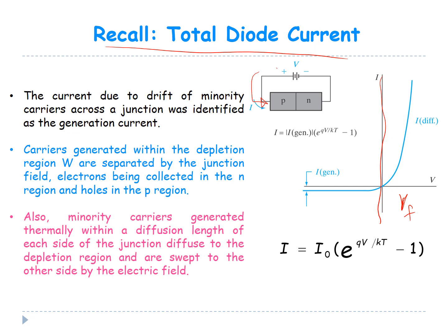So if you have your diode at equilibrium, where you've got a barrier which is equal to V0, like that, and under forward bias you effectively lower this potential barrier, so you get something like that, and your barrier here is going to be equal to V0 minus V forward. So it's going to be lowered.